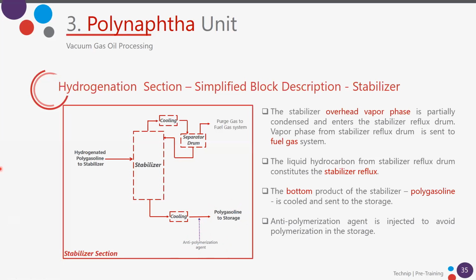So as you can see, the idea of this section is that you hydrogenate part of the olefins content that you have from the oligomerization section. This is done to meet the specifications of the olefins content in the gasoline. As design basis, you will hydrogenate 50% of the olefins content in the feed.